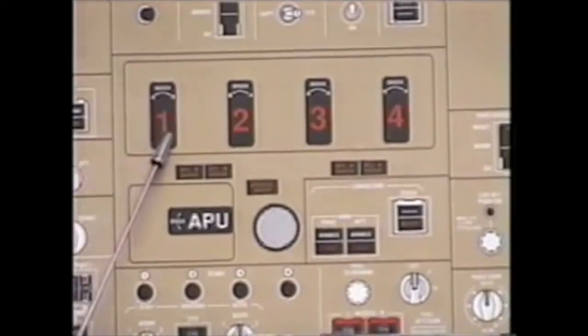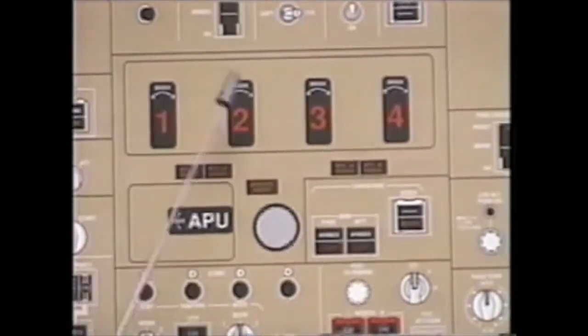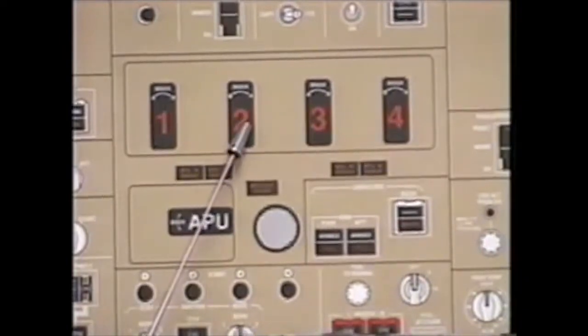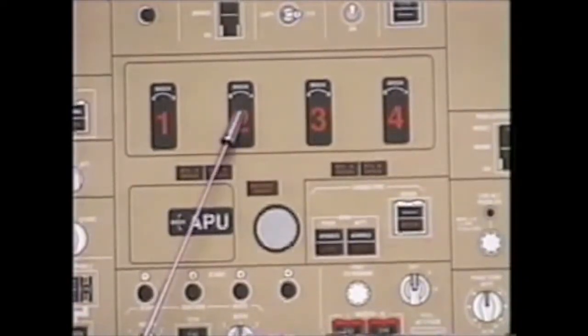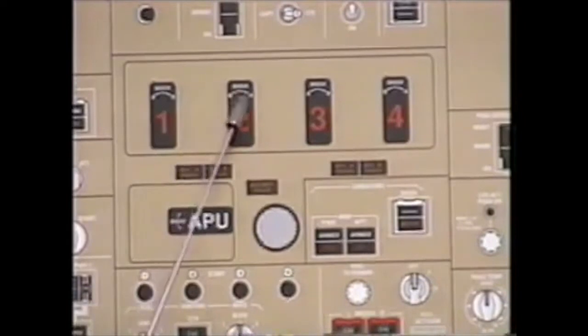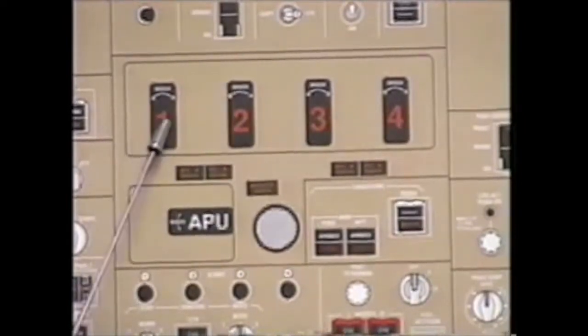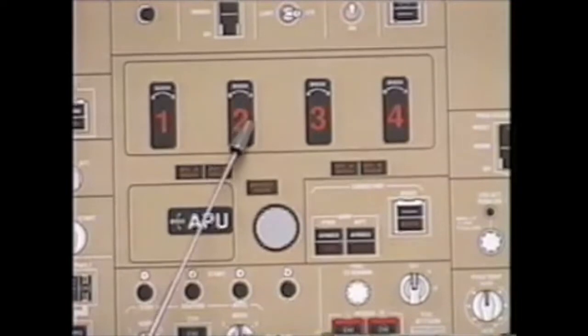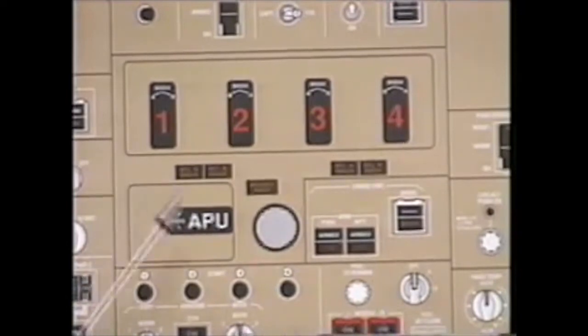If you discharge one bottle into one engine, you can discharge the other bottle into the other engine by rotating the handle in the same direction. If you notice, the control handle shows left on engine 1, for example, is A, left on engine 2 is B. If you were to pigeon toe the fire handles, either toe in or toe out, that would discharge the same bottle. APU, only 1 bottle for the APU. Once that bottle is discharged to the APU, there are no other fire bottles available.